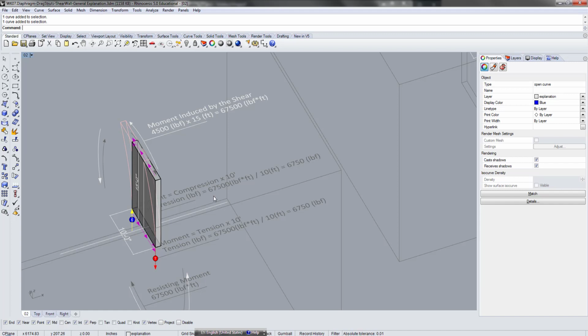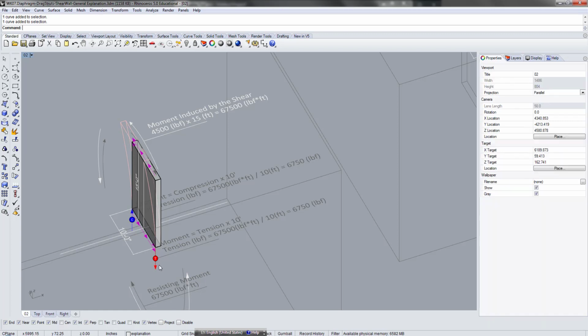That total amount of shear with wall height helps us calculate the exact number of this tension and compression at the base. What used to be this horizontal force has to get transferred multiple times, but at the end it gets resisted by a couple of tension and compression at the bottom.